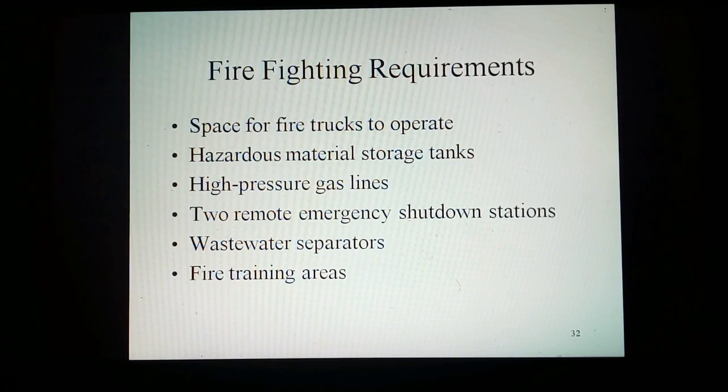Firefighting requirements. Each individual process unit shall be provided with sufficient open spaces there around that fire trucks can be run and operated thereat. The width of access way thereto shall be 6 meters minimum. Process units consisting of large hazardous material storage tanks should be located desirably in outer area in the complex site. High-pressure gas lines shall not pass through a process area or run within 30 meters of important structures or equipment without shutdown valves to ensure that portions of piping within the process area can be isolated from the main gas line and depressurized in the event of an emergency.